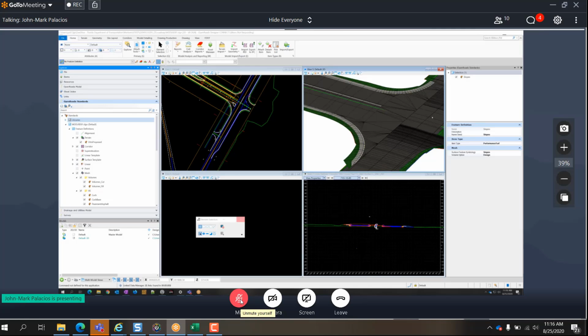we're not going to be showing end area. We're not going to be showing the volumes on the cross sections anymore. That's changing, yes. That's one thing to keep in mind. So if you're thinking that, oh, I need to have the volumes on each cross section, no, not for ORD projects. But isn't that coming from the 900 series? You still have the 300 series that calls for those. Yeah, and the thing is, I do have a project that's in production in November. And if you're following that 300 series, that's going to be a manual process. Okay. I can show you where they are.